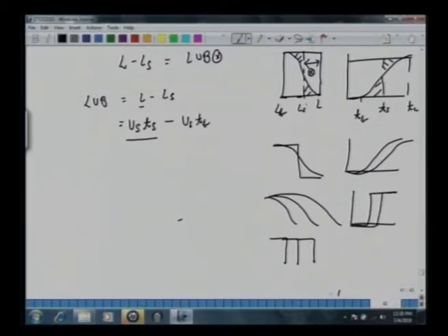So we define this quantity LS, and we move this region from here to here, to make a note that this length gets saturated when the front has reached LS. So that is US times TS. And then we have this LS, which would be US times TB, the time at which the first breakthrough takes place. At that time the ideal front would have been right here.